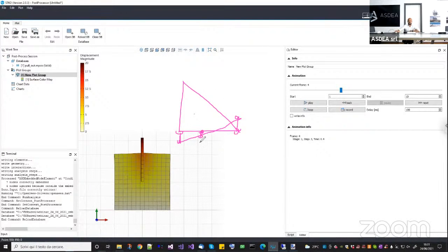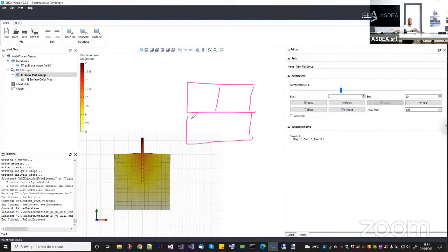And this is actually very useful, not only for embedding something, but also for attaching different meshes. For example, if I have a mesh here made of just two elements, and I have another mesh here which is much denser, like this, I can apply this constraint, and this node will move on this edge. Same thing for this node, it will move on this edge, and all the others. So you can actually use it to do local refinement without propagating the mesh here. So it is very useful also to attach incompatible geometries, and it will make your modeling much faster.